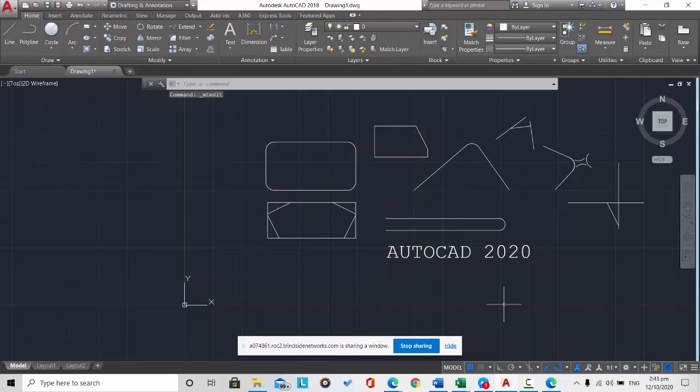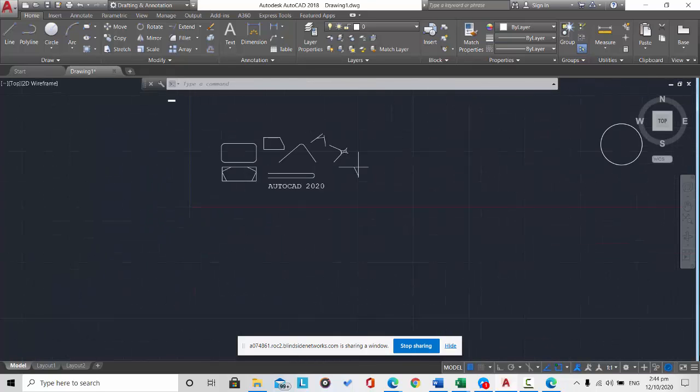See, that's the adjustment that happened, no? Because this one is the scale factor of 1. Okay? So you have to put in annotations. In annotations, you have to use styles and height of the text that can be readable, no? It should be readable. Like for example, in our drawing, we cannot use styles that cannot be read.